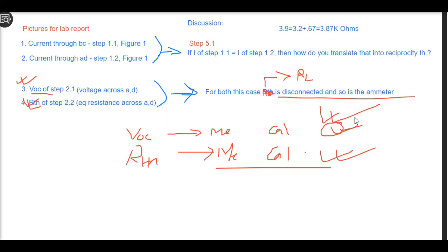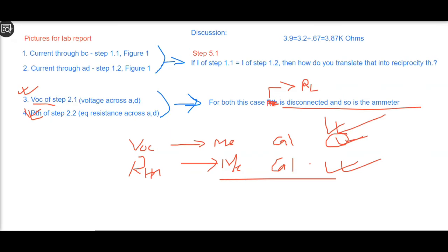For the power transfer theorem, I'm going to coordinate with the other TA. We are going to come up with a circuit that has an open circuit voltage, or the Thevenin voltage, of at least 4.5 volts, so that we can complete the readings of the maximum power transfer theorem as well, and you guys will be able to practice that in lab.